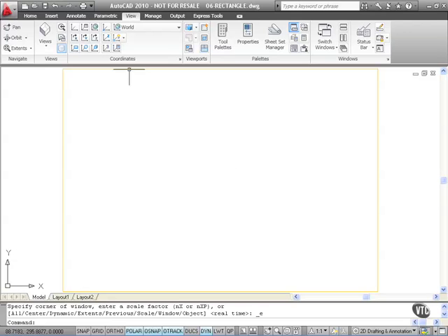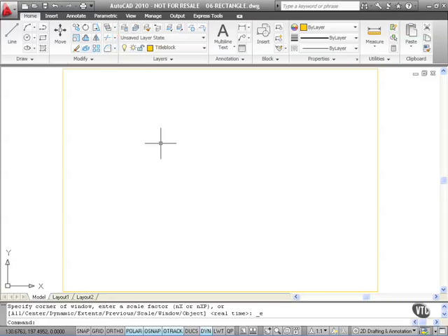I'm going to go back now to my Home tab, and we're going to utilize the Offset command on the Modify panel. The reason that we're going to do that is because this is a polyline, as you can see, one whole object, so we can offset the whole polyline to offset the rectangle and create some more rectangles inside this rectangle that we're going to utilize to create our title block. Offset is available on the Modify panel, and we're looking here for Offset.